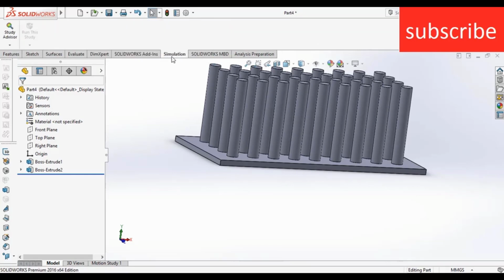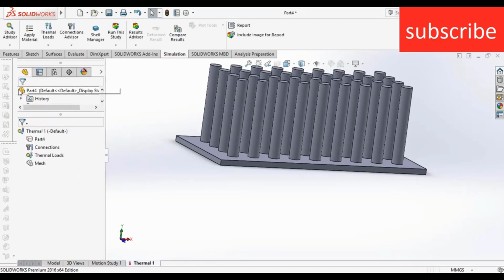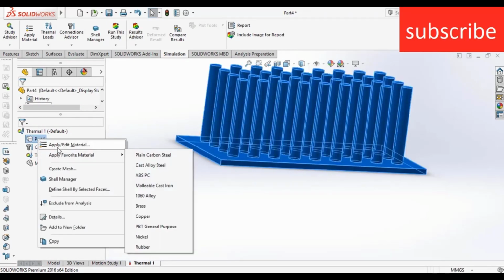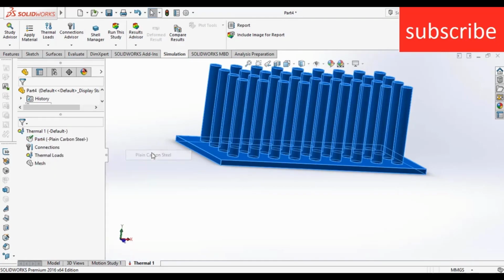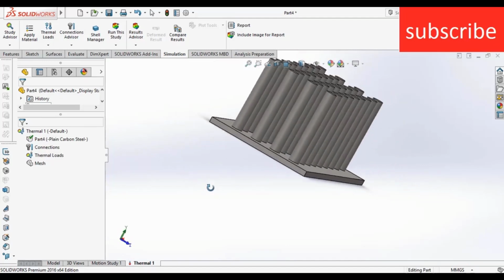After that go to simulation. Now click on study advisor, make sure you click on this arrow and click on new study. Now select thermal because I am going to do a thermal simulation in Solidworks. Click OK. After that, the first thing we need to do is apply material. So right click on part 4, click on apply favorite material, select plain carbon steel. So this material is now plain carbon steel.